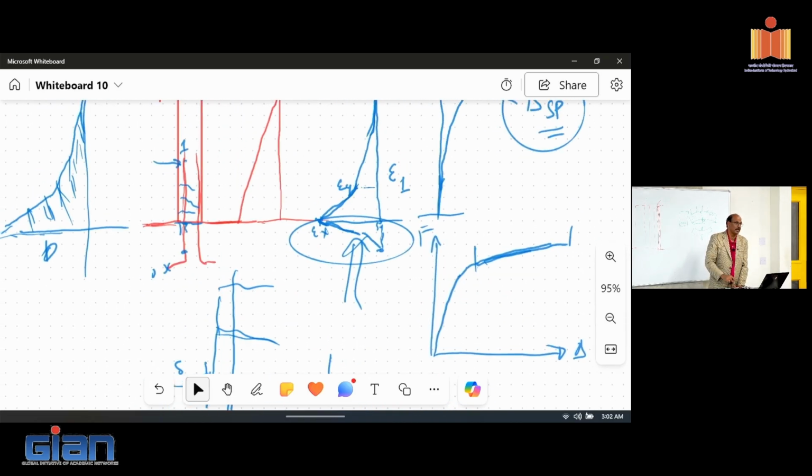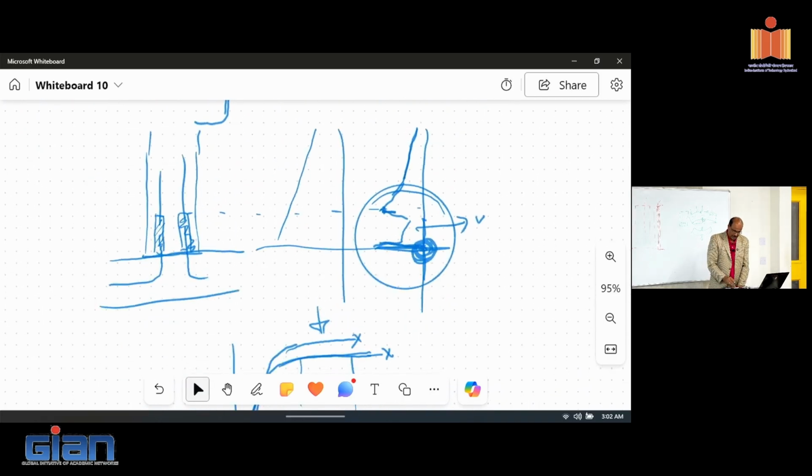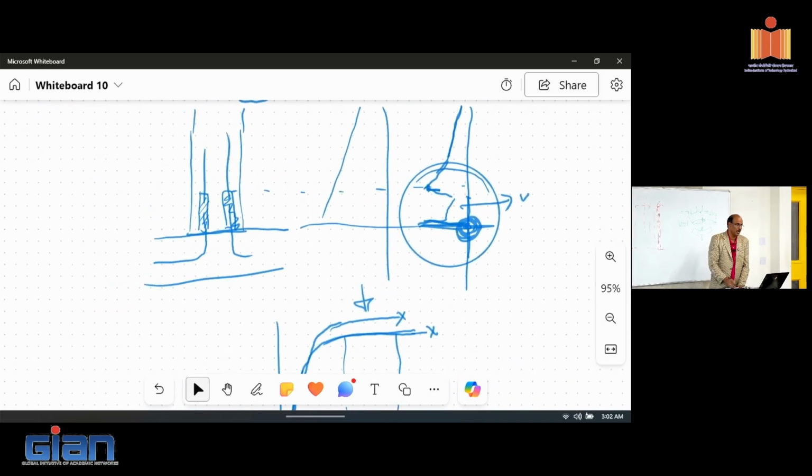So if you look at the crack, I think yesterday when you guys showed the pictures, it's pretty obvious. This will have a good uniformly distributed crack. So the damage, the spread of plasticity or plastification, is going to be more uniform in a cast in place. Here, because you put the coupler, you're going to have a crack maybe at the interface. The rest of the cracks are going to be here. And they may not be distributed much because of the strain demand; you may end up creating one or two concentrated cracks, and that's about it.